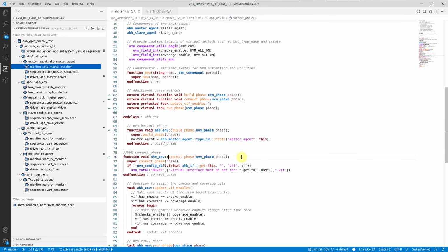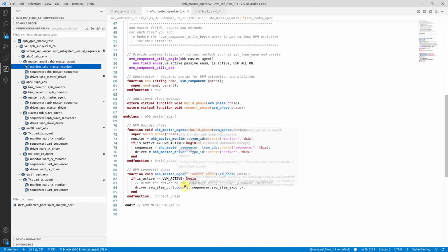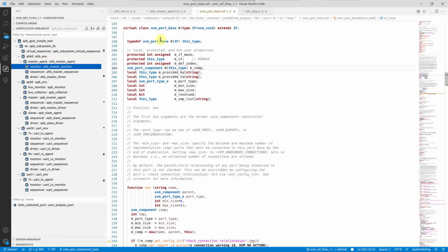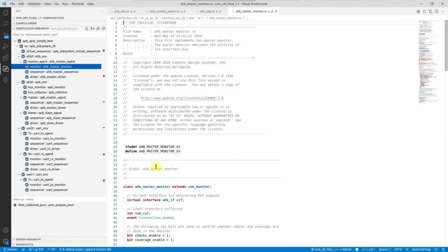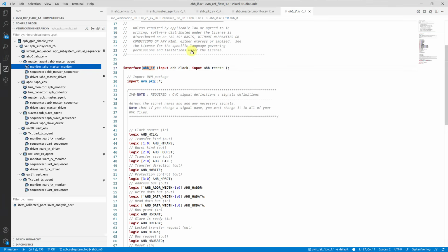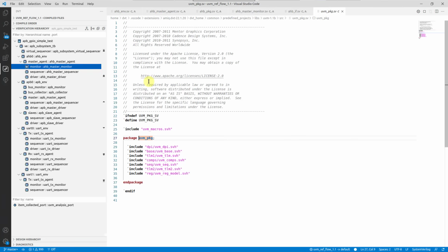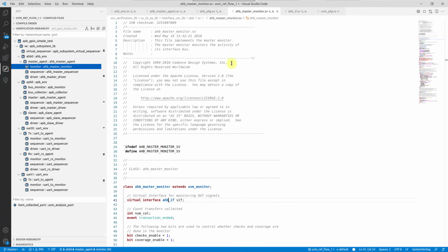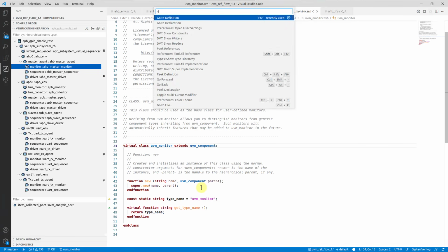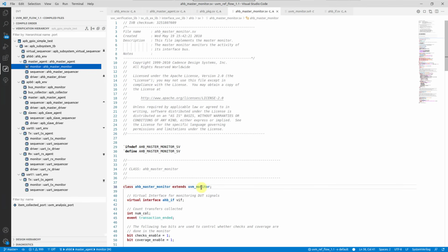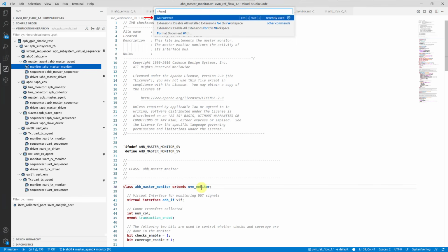You can also jump to the definition of any other language element: classes, methods, fields, macros, and even included files. Use the Go to Definition option from the context menu, or the command palette, or, easier, by holding down the Control key and clicking on the identifier. You can go back and forward between the visited code locations just like in a web browser.